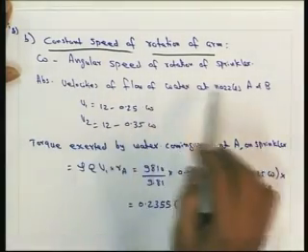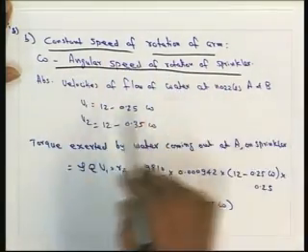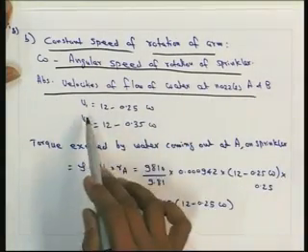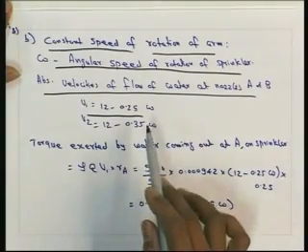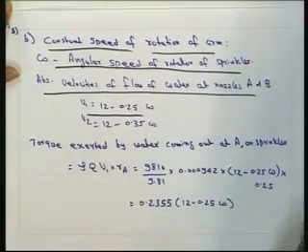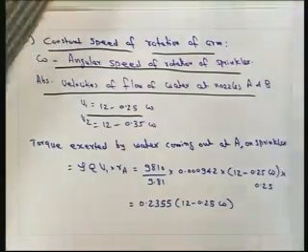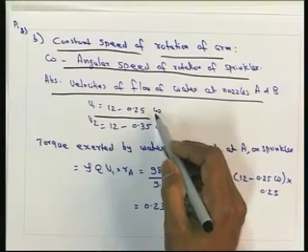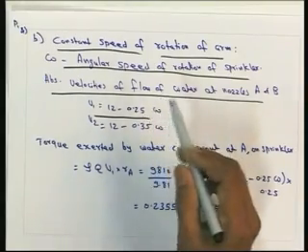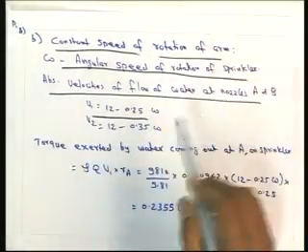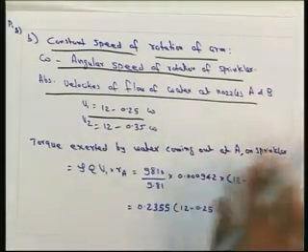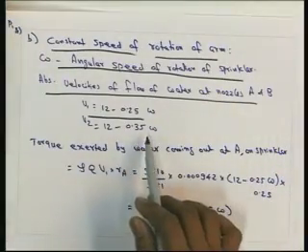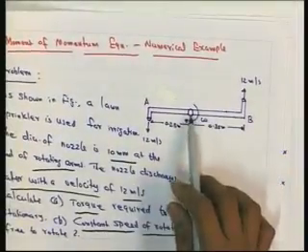So, if omega is the angular speed of rotation of the sprinkler, we can write the absolute velocity of flow of water at nozzles A and B. V1 is equal to 12 minus 0.25 into omega, where this 0.25 is the distance from the axis to the nozzle A, and similarly V2 at this location will be 12 minus 0.35 omega, since 35 centimeter is this distance.